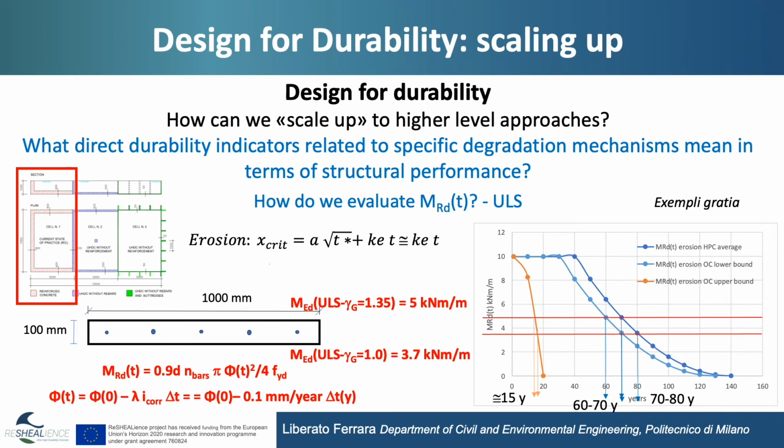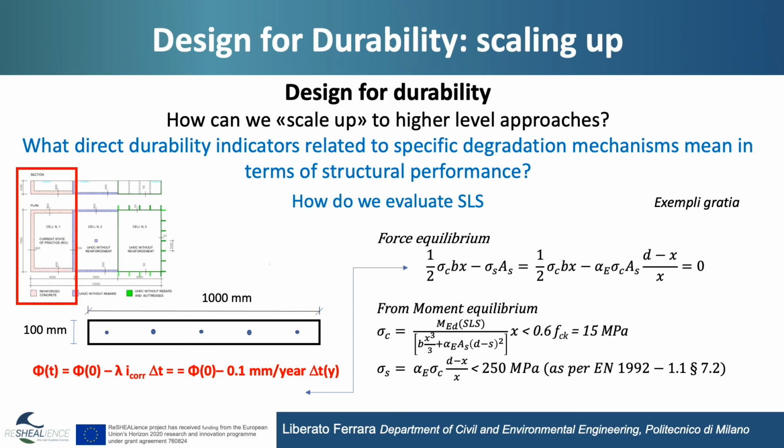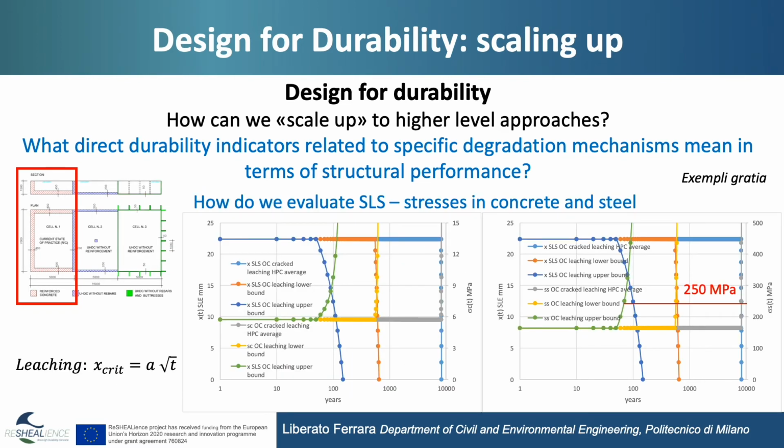Well, also in this case, we have then to evaluate the serviceability according to the same equations, force and moment, calculate neutral axis and stresses. And you can also see here, we have in light blue, orange, or dark blue, the curves showing how the neutral axis depth decreases. It's important, these parameters, because as you will see in the MOOC related to the design of this prototype, the depth of the compression zone is a design parameter, and you have to guarantee a certain compression depth because it's that which guarantees water tightness.